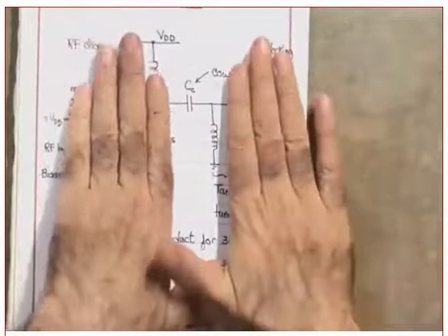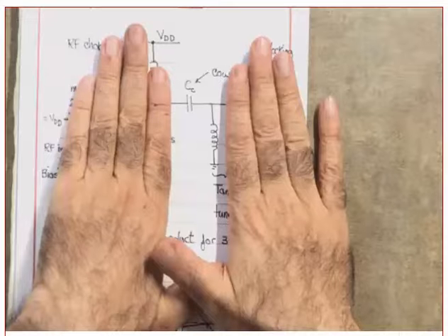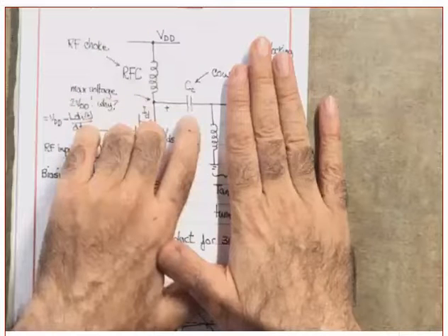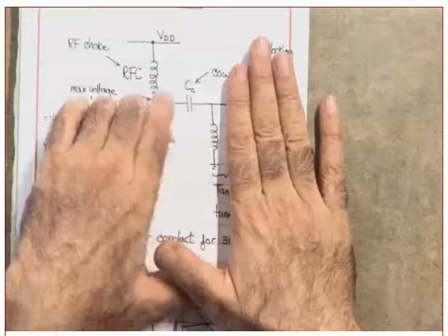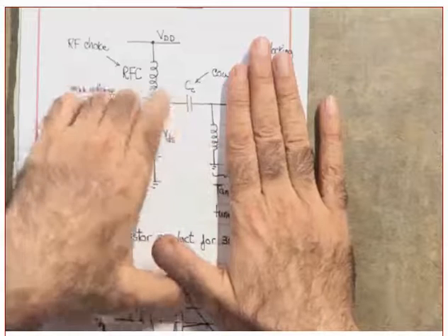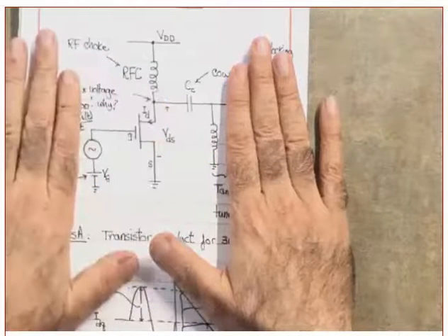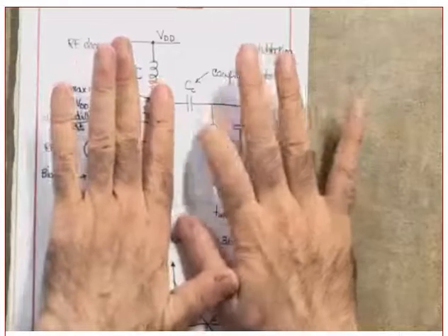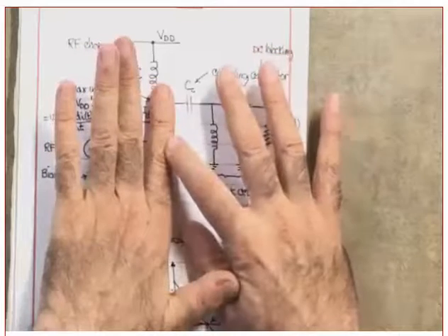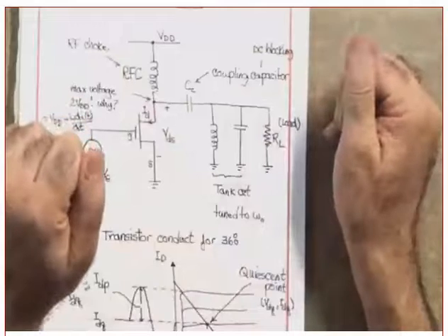Now, I want you to see this circuit. Don't look at this one here first. This. What is this for? This one could be used as a matching circuit. Do you agree with me or not? That's the L matching circuit. Now, this one is behaving as a what? As a DC blocker, but it could also be used as part of the matching circuit. Yes or no? Okay. Notice, by the way, if there is also an inductor here or a capacitor here, it could be a pi matching circuit rather than just an L. Are you losing me?